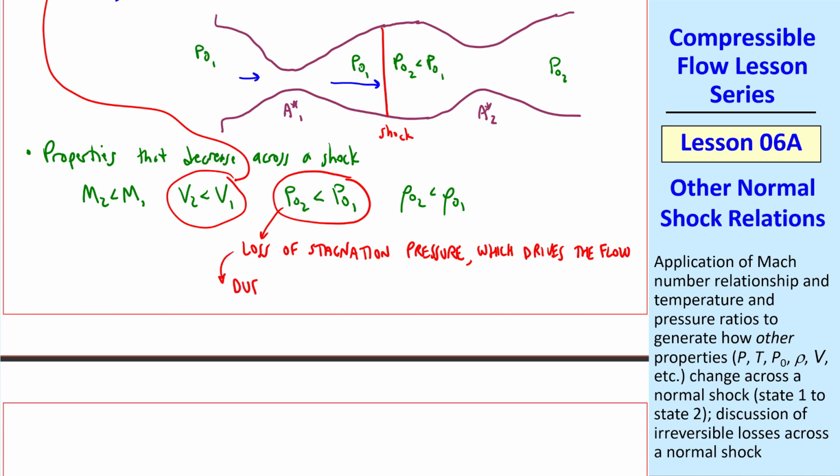This loss is due to irreversible losses and an increase in entropy across the shock. We've lost some of what I call oomph to drive the flow. If you ignore everything upstream of the shock and start with the stagnation pressure p02, you have much less oomph to generate this flow for a given back pressure, since it's the ratio of p0 and pb that determines this flow.